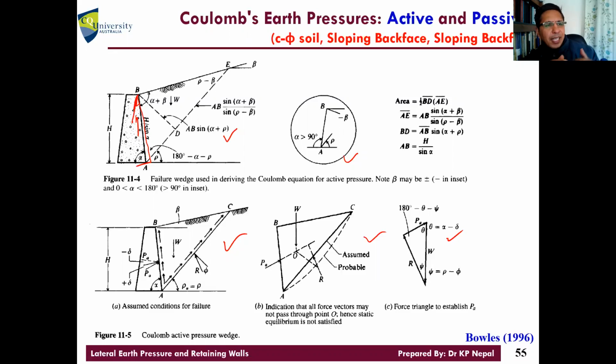So for different types of soil, we use different coefficient calculation formulas. Now Coulomb's theory is the main one when friction between wall and soil is assumed, which is in fact correct. But in reality, many people don't want to compute these complicated equations, so in many cases they use the basic Rankine's theory. But Coulomb's theory is more scientifically accurate for calculating these things.